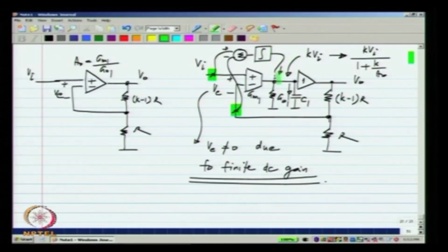Okay. Now, this gives a different class of op amps known as feed forward op amps, which we will discuss in the next class. Now, one other thing that we can guess right away is that we are assuming that the original circuit reaches steady state and based on that steady state error we are doing the integration, but the integration itself is a continuous operation. What this really means is that the second integration that we have here is much slower than the first one. Okay. It almost looks as though the first one reaches steady state and based on the steady state value we inject some current here.